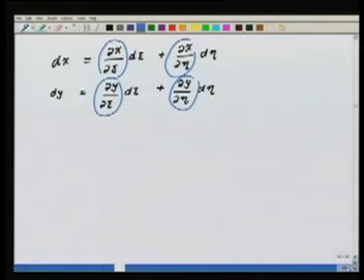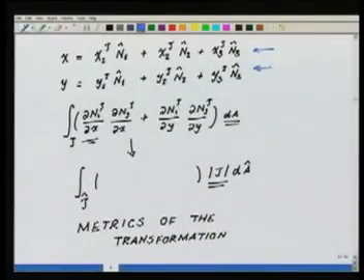Okay, so one can show from that expression that we have there that del x del psi is equal to x2 of tau minus x1 of tau. Let us go back and see. Here, if you remember, n1 hat was 1 minus psi minus eta, n2 hat is psi, n3 hat is eta. So if I take this definition and go back, dx d psi will be equal to x2 minus x1.